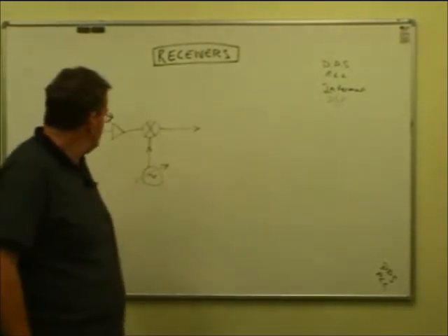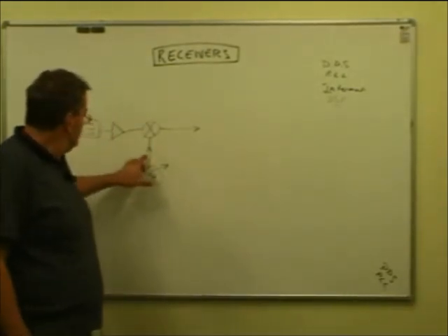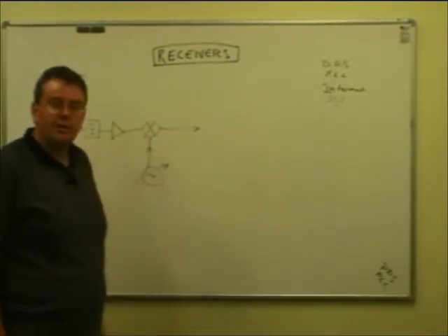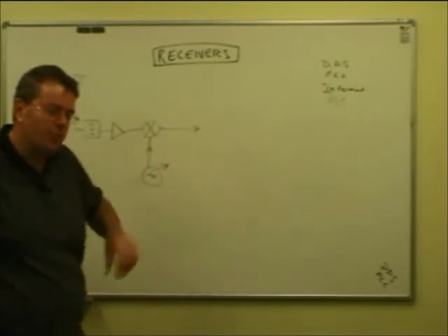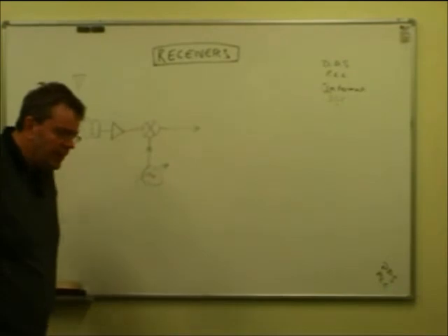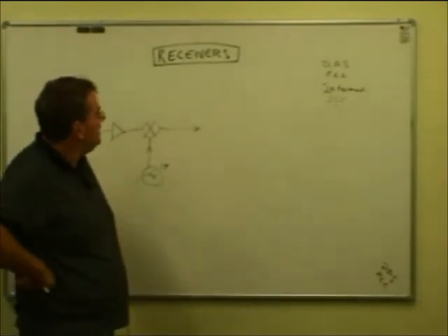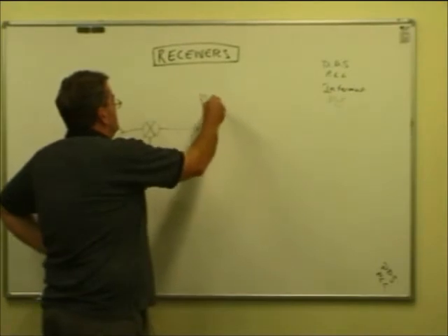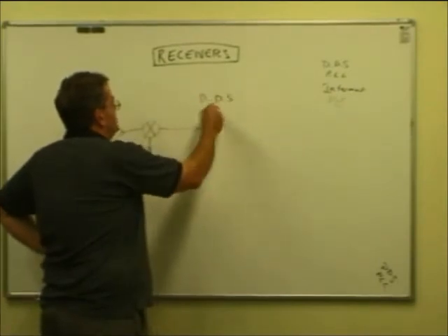And it worked reasonably well. It did have problems though. It tended to produce quite a noisy signal. The oscillator wasn't as clean as the free running one, and noise on your oscillator has the same effect as noise on your signal, and there are other problems with it as well, but it could degrade your receiver performance.